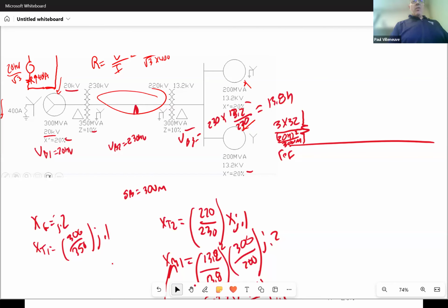All right, so current can flow up through the neutral, so I have a connection. Now I'm going to show my generator. And now it's time to go to the transformer. Can zero sequence current flow into the delta connected winding? No, it can't. So I have to stop right there. No zero sequence current flow. It can't go in or exit the transformer on the delta side.